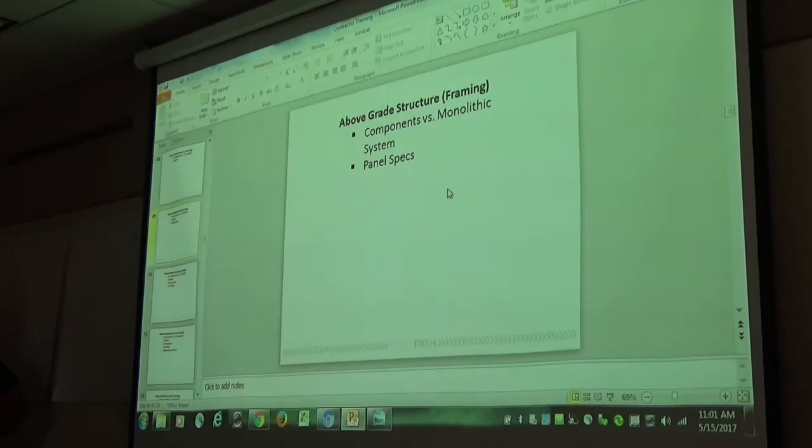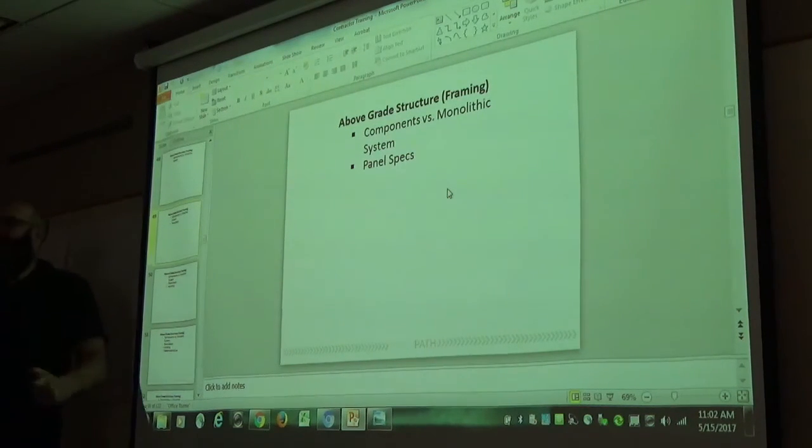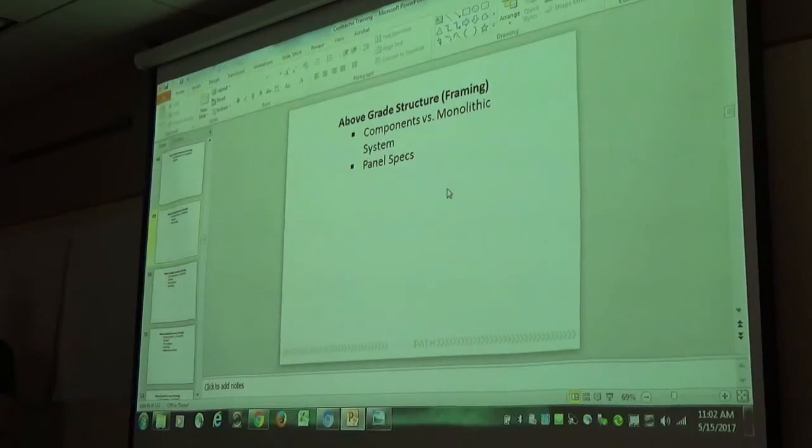shoestring video I saw on Facebook or on YouTube of somebody demonstrating the different qualities of OSB out there. They were in a shop and they laid out 4x8 sheets of 5 different brands. You know, it's Norbord and GP and then the Advantech, and he goes to the first one and jumps on it, and it snaps, and goes to the next one. It was tilted up, right? Yeah, one end was on a table and one end was on the ground. And he did that, it broke all 4 of them, got to the Advantech, and it just bounced, right?